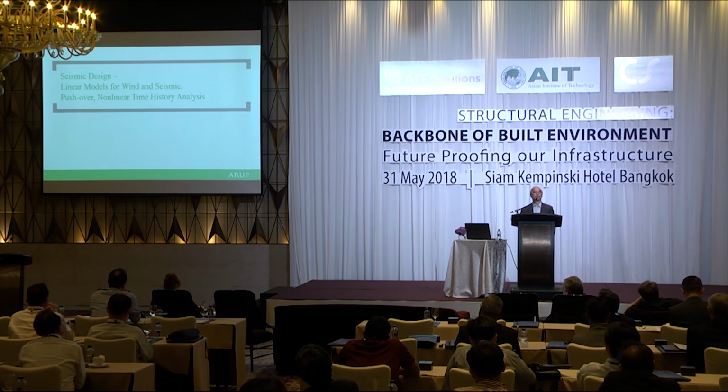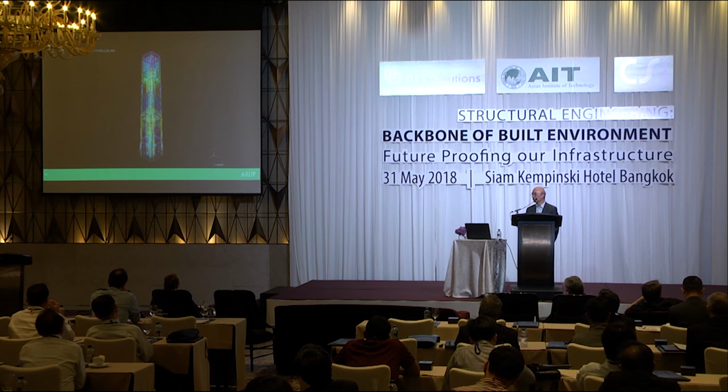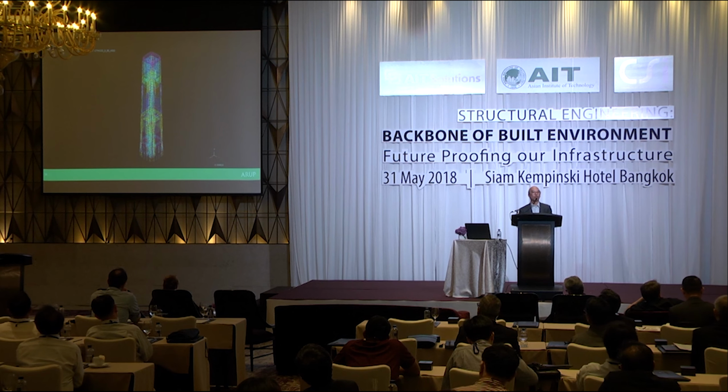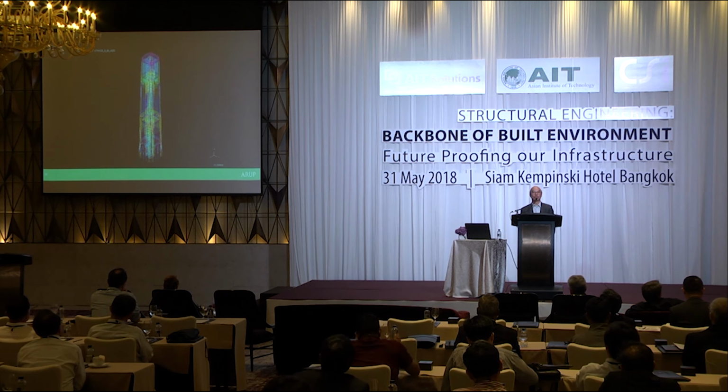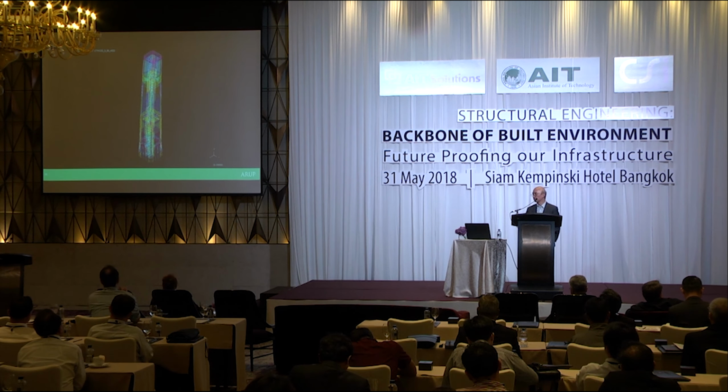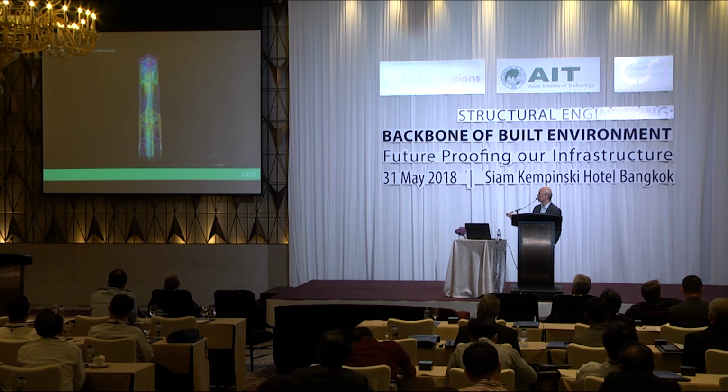And so for structural engineering, when we do the design, especially for tall buildings in seismic areas, we have to go for performance-based design. One of the challenges of performance-based design is that we need to go for nonlinear time history, because we need to know how the structure behaves in a 2,500-year earthquake, where some of the members get yielded, and so forth. And you can see how this building moves.